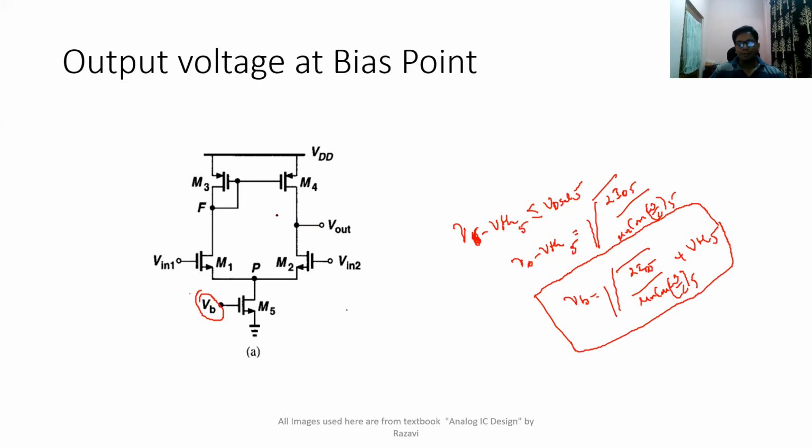Okay, and one important thing which I've missed to address about this amplifier is this amplifier doesn't have two outputs, unlike the earlier amplifier which we have seen, where there were two resistors and two transistors we have taken here, right? So there you were getting two outputs, V0 plus and V0 minus. Okay, here unlike that, this is going to have only a single output, which is here. So this amplifier is also called a differential input single-ended output amplifier. So this was all about the large signal analysis of this amplifier.